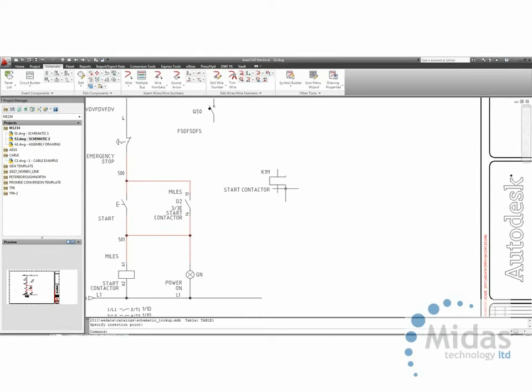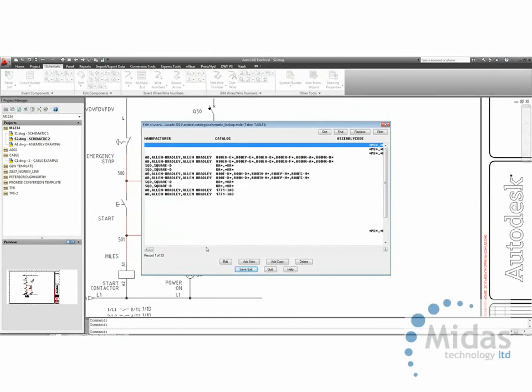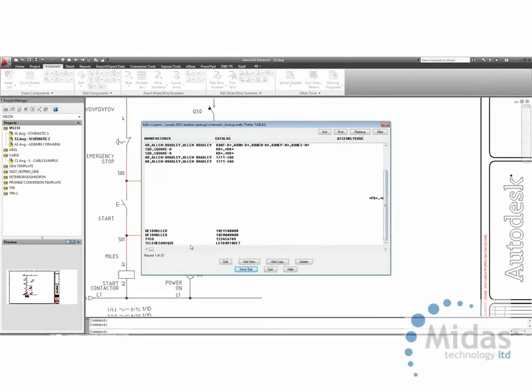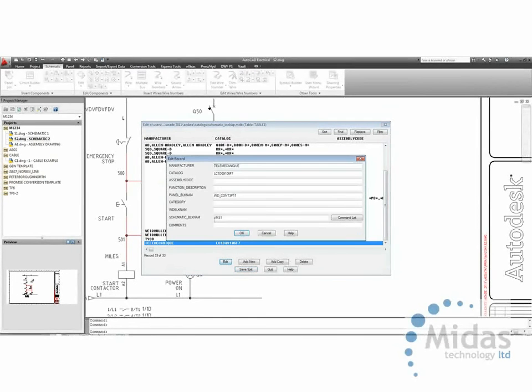So, as I mentioned, that automatically offered me a block called VMS1. When I placed the push button down in the schematic, it automatically offered me a VPB11 or an HPB11 as the option for the switch. Why did it know, and how did it know which schematic symbol to associate with that particular part? Well, there is what's known as a schematic database file editor, and the schematic database file editor holds that type of information. So as an example, the Telemecanique LC1D09106F7 that we've just placed had a schematic block name of VMS1.